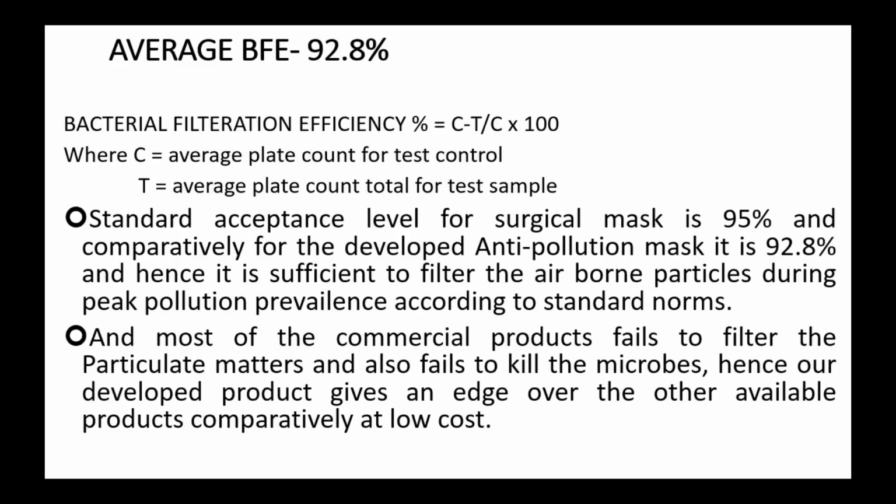So the standard acceptance level for a surgical mask is 95%. And comparatively, my mask has achieved around 92.8, nearly 93%. Hence, I conclude that it is sufficient to filter the airborne particles during peak pollution prevalence according to standard norms. And most of the commercial products fail to filter particulate matters and also fail to kill the microbes. Hence, our developed product gives an edge over other available products, comparatively at low cost also.